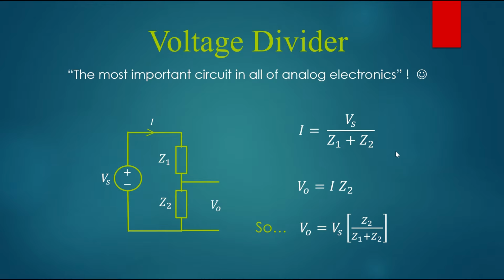I always tell the students that because this thing just appears a lot in circuit analysis. It really helps to visualize things this way. Let's say you have 2 impedances that are in series like this, and you put a voltage across those 2 series impedances. And then you look at the voltage across a single one. Here it's Z2 that we'll look at the voltage across. What you find is, according to Ohm's law, the current is the total voltage divided by the total impedance, which is just the sum of the 2 impedances.